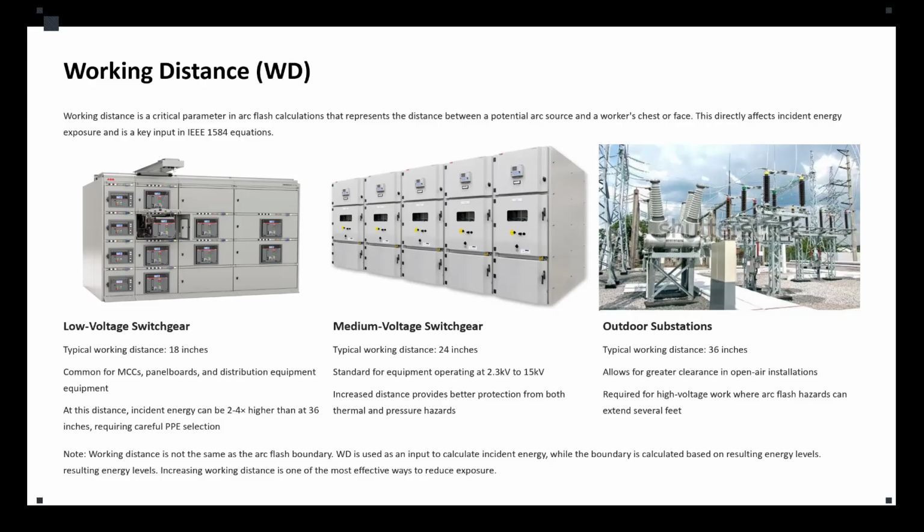Now, this distance is not a guess. It's an assumed fixed geometry used to calculate how much radiant heat will reach the body in the arc flash scenario. So the closer you are to the arc source, the higher the incident energy. The farther away you are, the safer you are. This concept is similar to standing near a bonfire. As you move away, you feel less heat because thermal radiation dissipates with the distance.